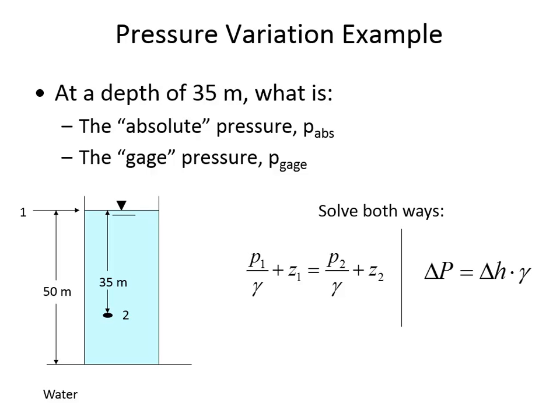And when we say absolute pressure, that's assuming that this location is at sea level, where the atmospheric pressure is 101.325 kilopascals. And so the pressure of the atmosphere in this example is going to be 101,325 newtons per meter squared. All right? So, hop to it. Go ahead and calculate the pressure.